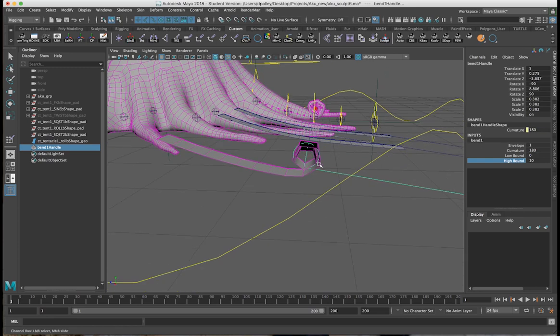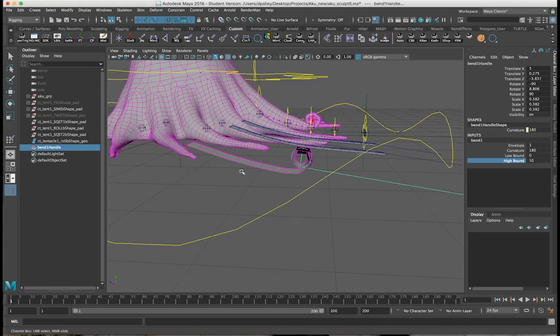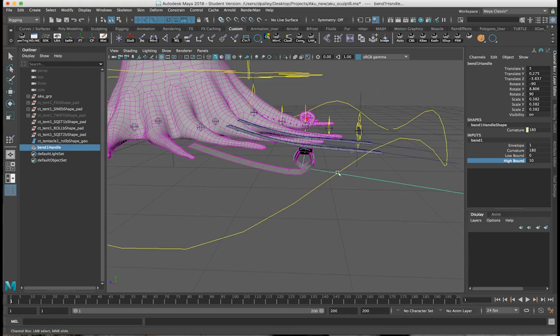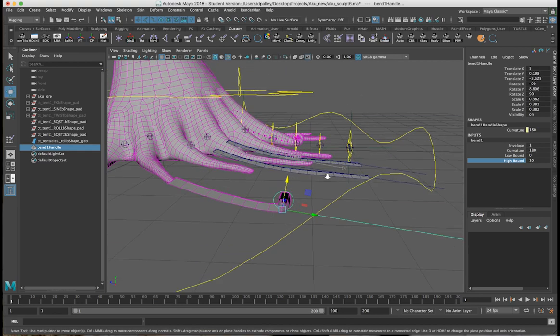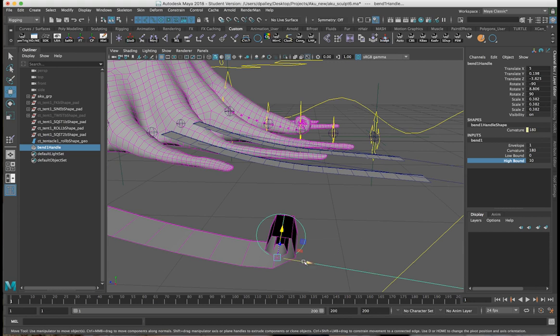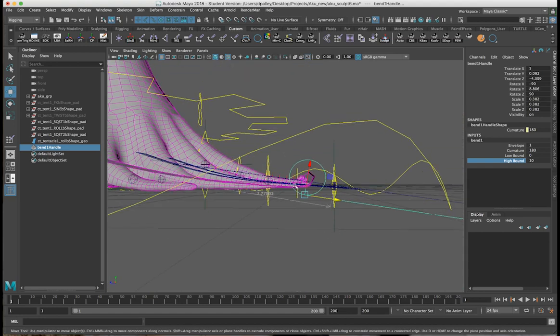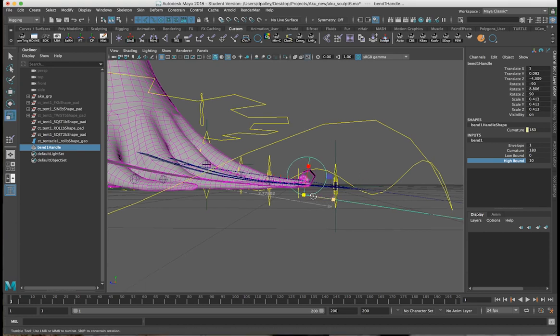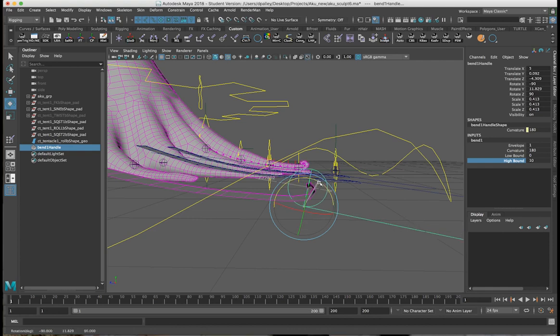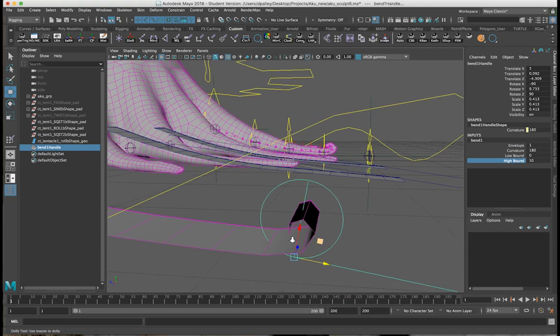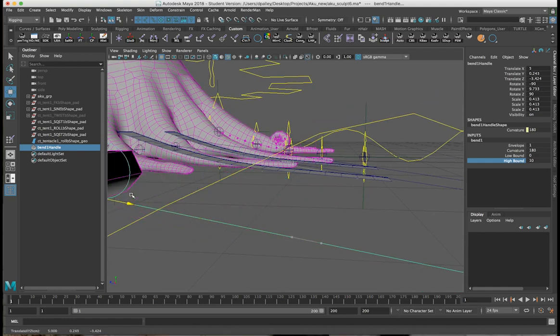But by default, this works much better if the geometry is flat. Normally, if I coil the tentacle here, you can see what happens to the original. Even if I move it back and forth, you see it kind of collapsing in on itself. Because by default, it's designed to only curve into itself. So normally what you would do to fix that is rotate it just a little bit, so you can get that proper coiling effect, and kind of rotate in on itself.